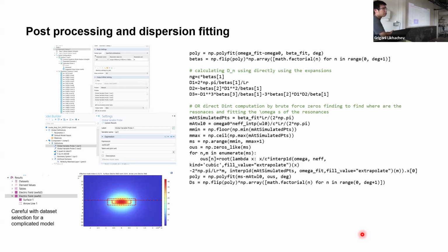It's a bit more convenient, but I experienced that it has a bit less precision than COMSOL. Also, when you are doing the meshing for the mode solutions, you can only have rectangular grids. So to discretize your waveguide geometry, you will actually need many more grid points to have a precise description. For example, if you are varying your waveguide height.